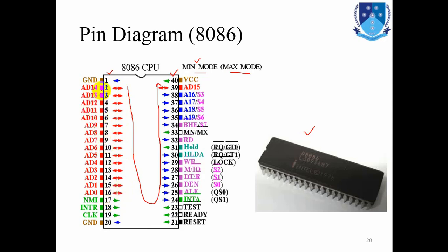Pointing out means that it is an output pin of that IC. Bidirectional pins mean the microprocessor can receive and send data or signals on these pins, while the green incoming, pointing-in pins represent that the microprocessor is receiving data or signals on these pins.